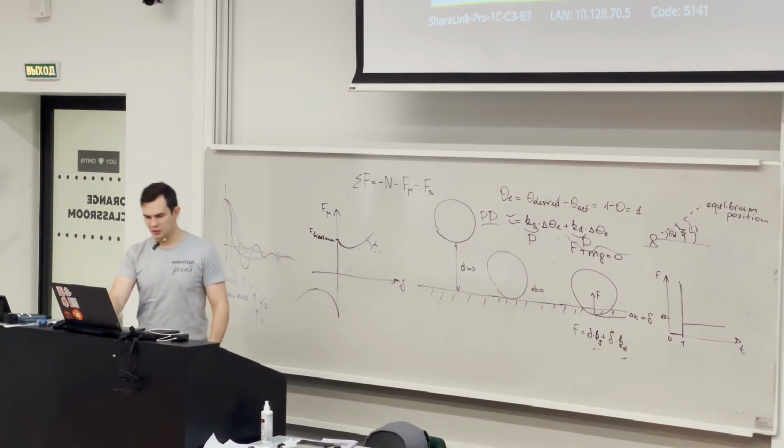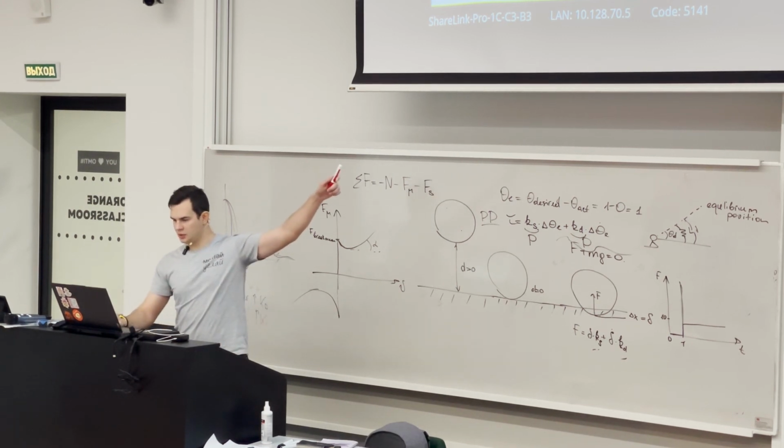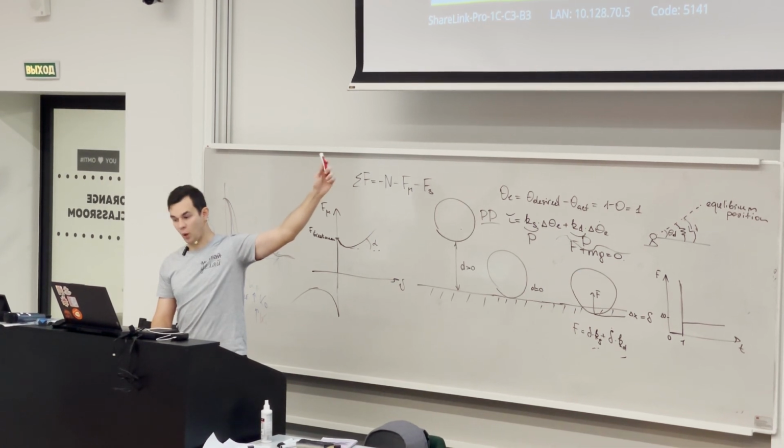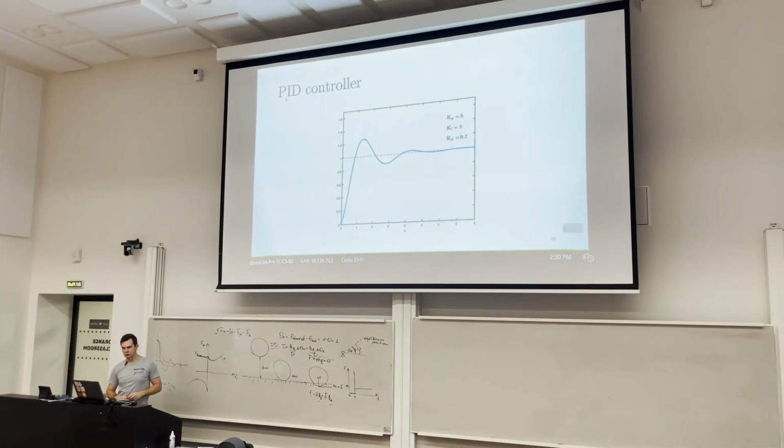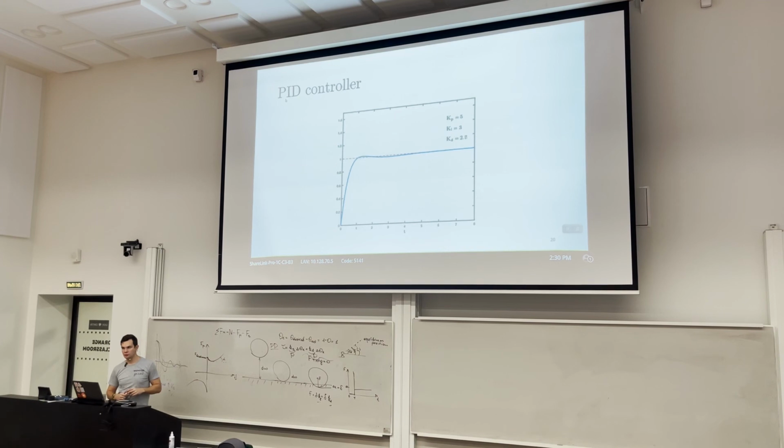So right here in the animation, you can see we're increasing the P component, now the D component, the I component, and now the D component in order to get rid of overshooting. So once again, we increase Kp proportional, then integral to eliminate steady state error, and then damping.